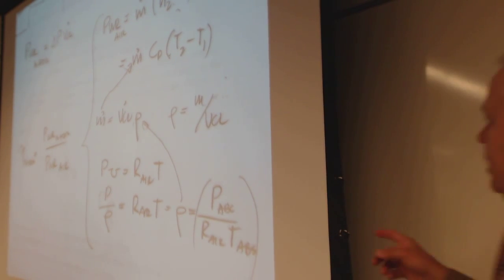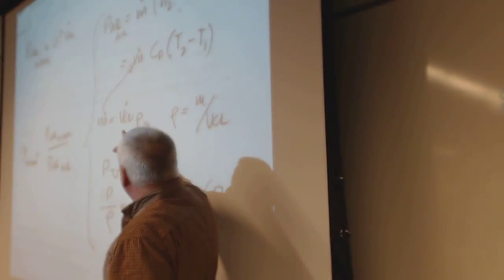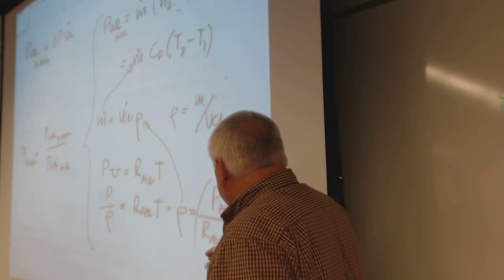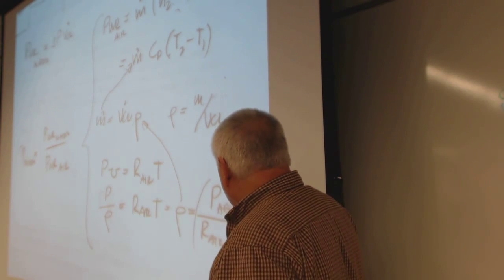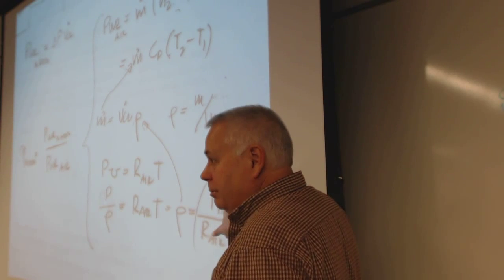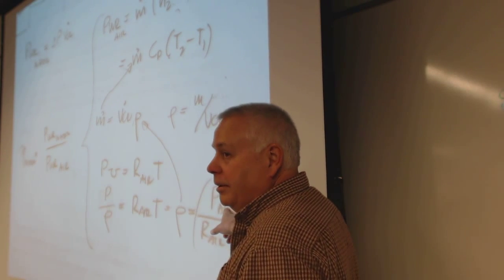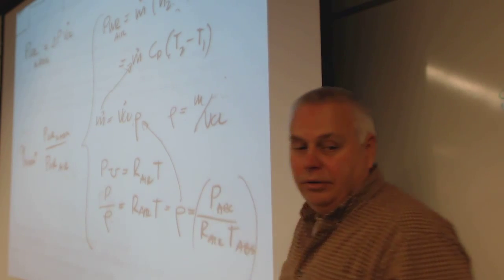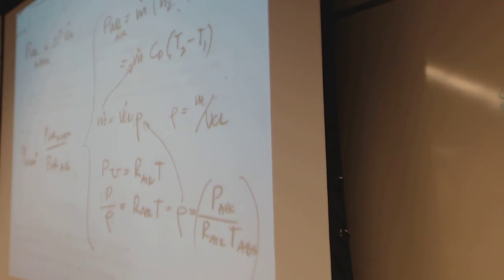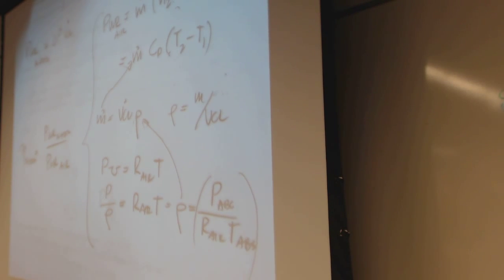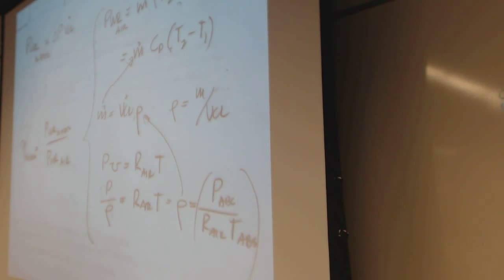We need the density at the point where we're measuring the volume flow rate. Should we also measure pressure there so that we can get all of that data? So your data sheet says temperature, pressure, and with that pressure, make darn sure it's an absolute pressure.